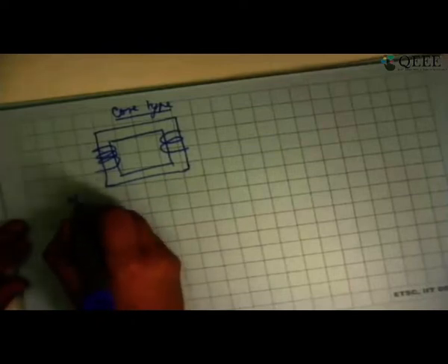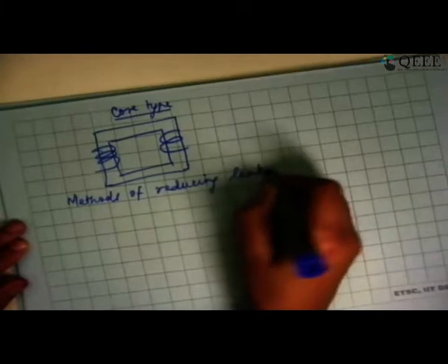So if I have one limb here and another limb here, you would be able to see the windings clearly in both the limbs in the case of core type construction. This is true for core type. Whereas in shell type, in all probability, you may not be able to see the windings at all. That's how you can recognize whether it is core type or shell type. Just by looking at it, it's difficult if you have the enclosure around the transformer. So one method of reducing leakage we had already seen, that is shell type construction. Let us try to look at the other methods of reducing leakage.